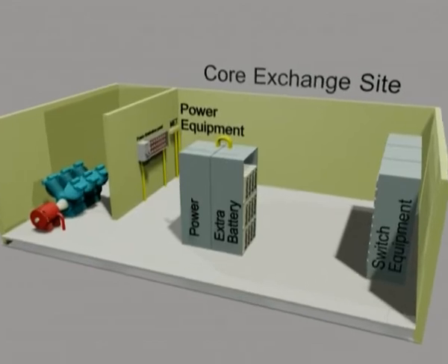If the batteries are supplying the load, then the voltage will start to decrease due to discharge. To maintain stable voltage within given limits, the battery capacity has to be correctly dimensioned with regard to backup time and the size of the load. With standby diesel generators, you can normally reduce the size of the batteries.